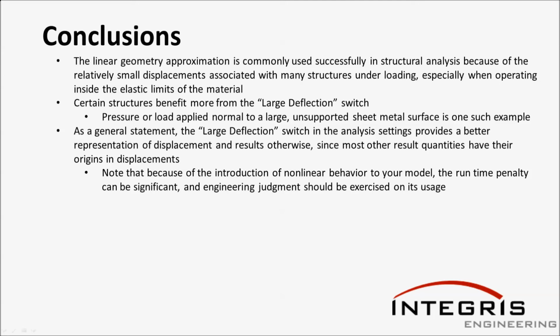As a general statement, the large deflection switch in the analysis settings provides a better representation of displacement and results otherwise, since most other results quantities have their origins in displacements. Note that because of the introduction of nonlinear behavior to your model, the runtime penalty can be significant, and engineering judgment should be exercised on its usage.